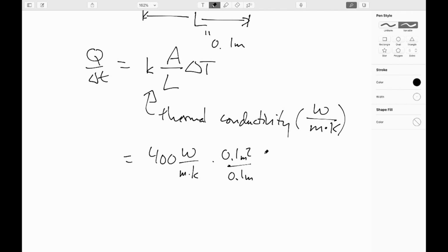And then our change in temperature, T final minus T initial, that's going to be 100 degrees C minus 20 degrees C. And if you subtract two Celsius temperatures, that's Celsius degrees, which are kelvins. But again, if you're not sure, you can't go wrong adding 273 to both of these and subtracting. The 273s will end up canceling out. And either way, you'll get that this difference here is 80 Kelvin.